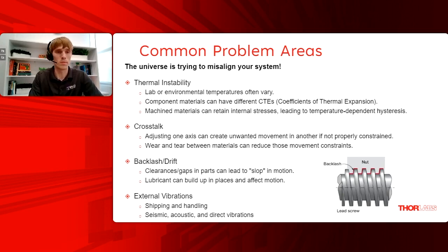your alignment stability. Think of the contact points of most mirror mounts where the adjuster screw pushes on the optic plate. Softer materials like some alloy steels or aluminum will deform faster than other harder materials, and those deformations create grooves or ridges or other items that could bias the motion by not properly constraining the movement across each axis.